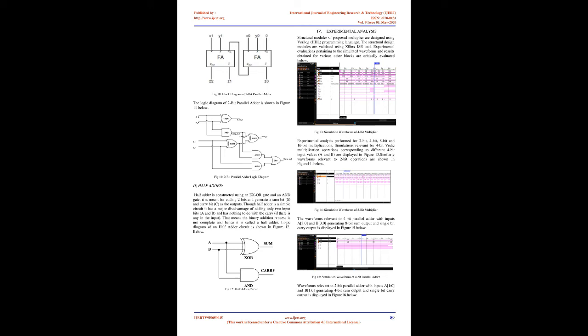A. 2-bit binary multiplier. The design of the 2-bit binary multiplier is meant for multiplying two 2-bit binary numbers and providing the result. The methodology of multiplication is based on calculating the partial products, shifting them, and adding them together. The logic diagram of the 2-bit binary multiplier, as depicted below in Figure 8, contains two half-adders and AND gate units. Fig 8, logic diagram of 2-bit binary multiplier. 4 such 2-bit binary multiplier units are employed for the overall top-level design unit.